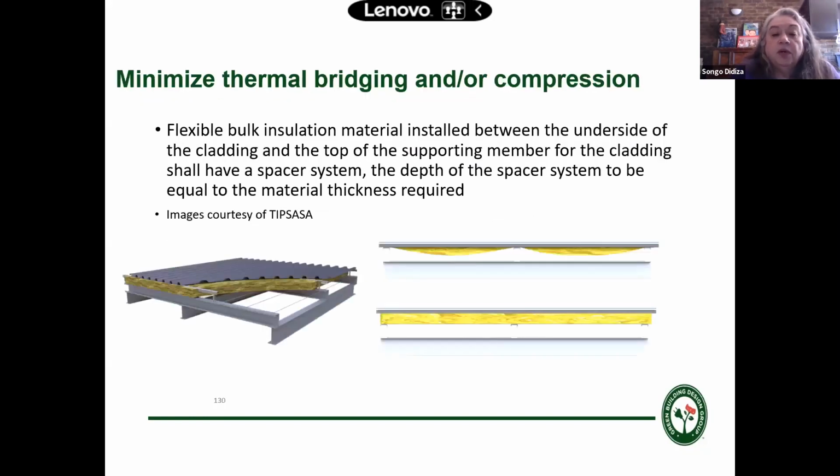And as I said, what we decided is, instead of changing the R value of the sealing systems, let's just make sure that the insulation systems that you put in buildings work better. I don't know if you've seen metal buildings, they normally have a blanket insulation, and it compresses at the purlins, and then you've got straining wires that hold it on. Each of these things, at the purlins, at the straining wires, it shrinks the actual thickness of the insulation.